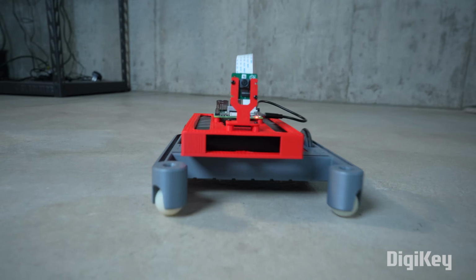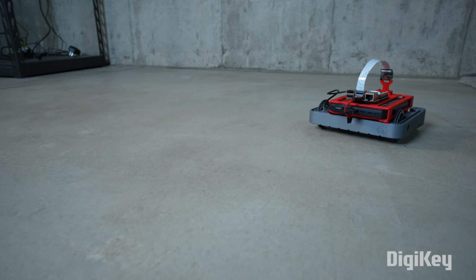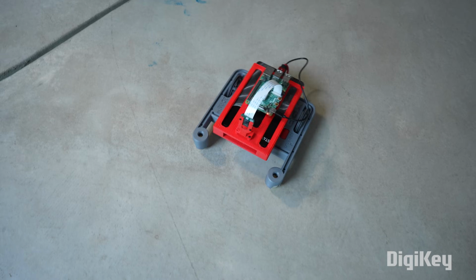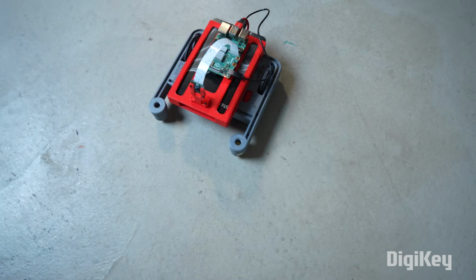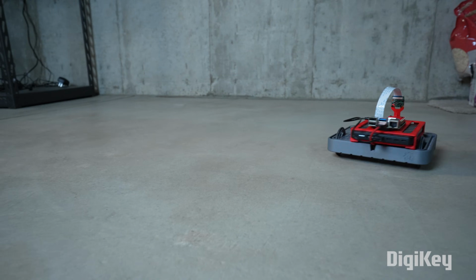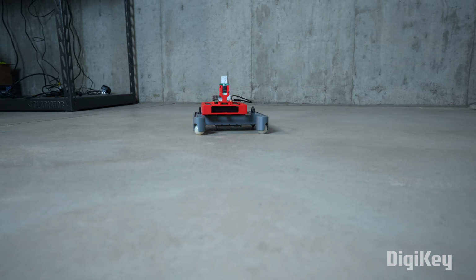If you set up SSH on the Raspberry Pi, you can log into it remotely in order to start your ROS program, which means you don't need a full keyboard and monitor setup. The program should start and the node should periodically tell the Arduino program how to control the motors. The robot should start, stop, and turn, just like we told it to.